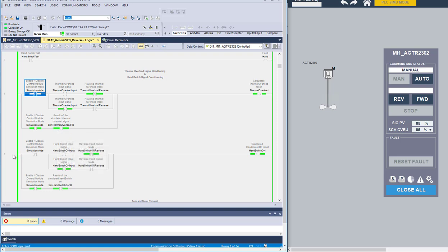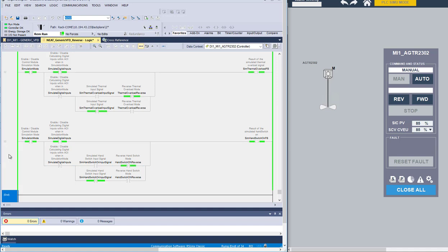And prior to that, I want to show you the on switch on, which is exactly the same logic. So we expect to have an on switch on at 1, a status 1 in the PLC. So we condition the on switch on input with a reverse bit to get this information set to 1. So in terms of simulations, I will go down into the code. So here I have my simulation thermal overload in rung 32.